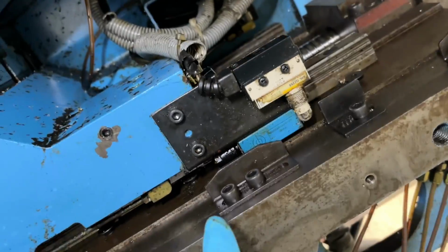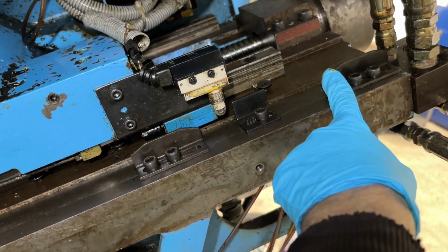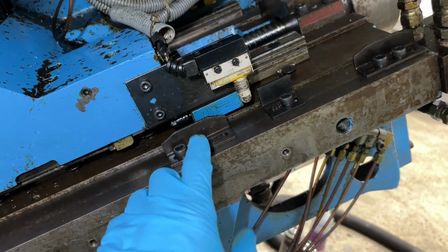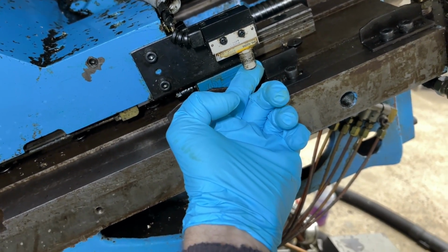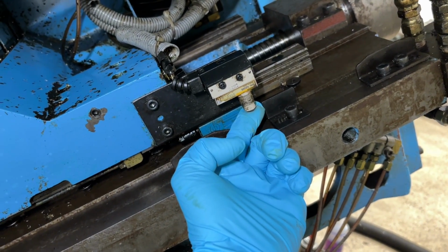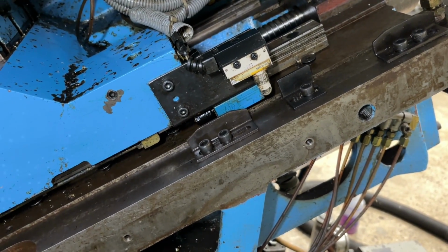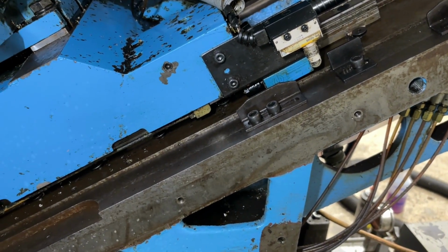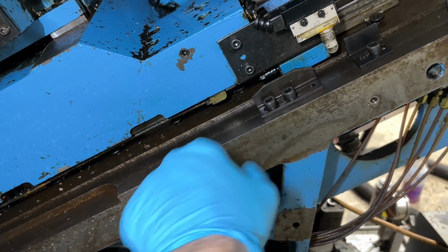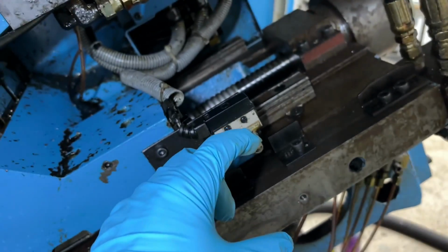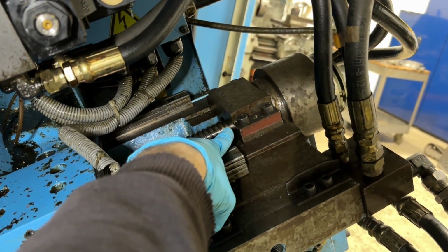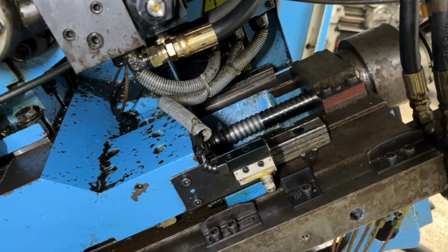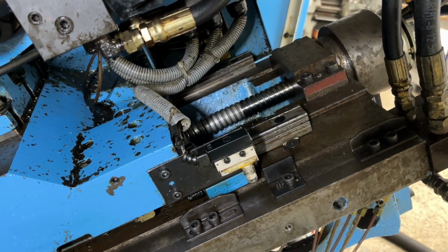So this is our limit switch, and these are the limit switch dogs. So this is the hard stop. So when you scroll your machine all the way down and it rides up onto this, it shuts down the hydraulic pump and pretty much makes the machine immobile. So it's a very important safety function, not just for the human, but if you can imagine if this wasn't here and you just jogged the machine all the way up into the ball screw bearing, it would just destroy itself, right? It would like rip itself out of the casting. It would be a bad day.